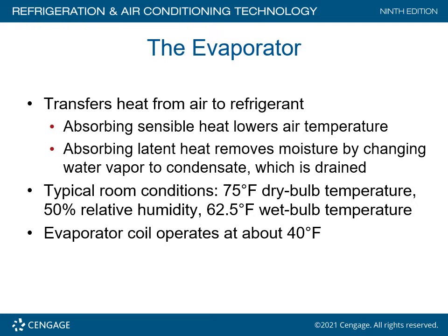Well, Larry, I'm not getting 40 degrees out of that unit on my house. Well, that's true, because remember, it's traveling through ductwork, it's traveling through walls, areas where heat is being absorbed into that temperature at the evaporator. We're talking about at the evaporator coil. Once it leaves the evaporator coil, the magic rule is basically add 10 degrees. So typically we would expect to see about 50 degrees on the supply outlets on a structure.